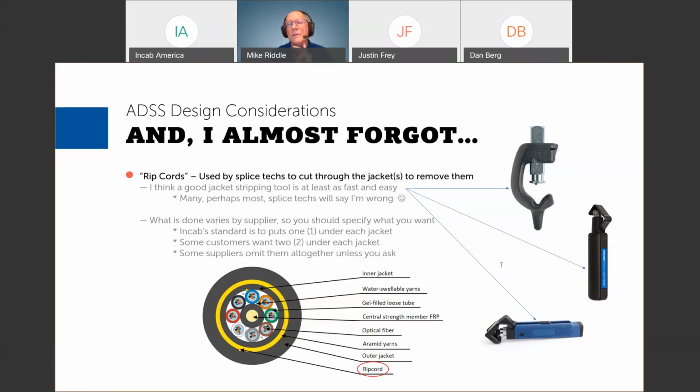And so to go back to the person who asked about using HDPE, well, HDPE in theory would be better for the dead end design again. But as a practical matter, I think the hardware suppliers design their stuff around the range of cables that are out there. And so the people using polypropylene and using medium density, they sort of factor that into their design.